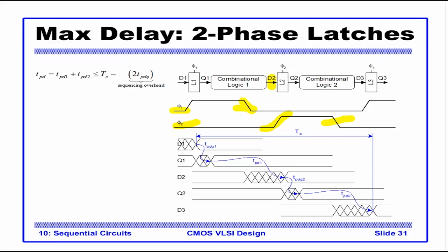A flip-flop based design will have just 1 clock going to multiple thousands of elements. If we replace that by latches and this scheme, we'll have to have 2 clocks, so adding 1 more clock adds again multiple thousands of overhead.